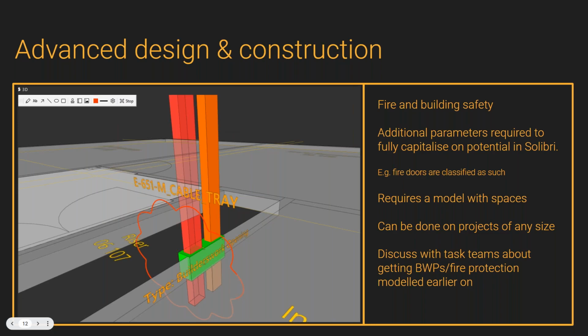Once more, this is a requirement that came about from discussions with build teams. Gathering builders work information in the traditional sense, where you're looking through drawings and schedules, can take quite a bit of time. Usually someone draws the short straw and spends, depending on the project size, one or two days getting all that info together into an Excel database. If we use a Solibri information takeoff, we can get that data pretty much straight away. So we've reduced the time taken for a task, and we've prevented any bottlenecks that arise in gathering that information. But it's worth mentioning that your models obviously have to be precise if that information is going to be reliable.